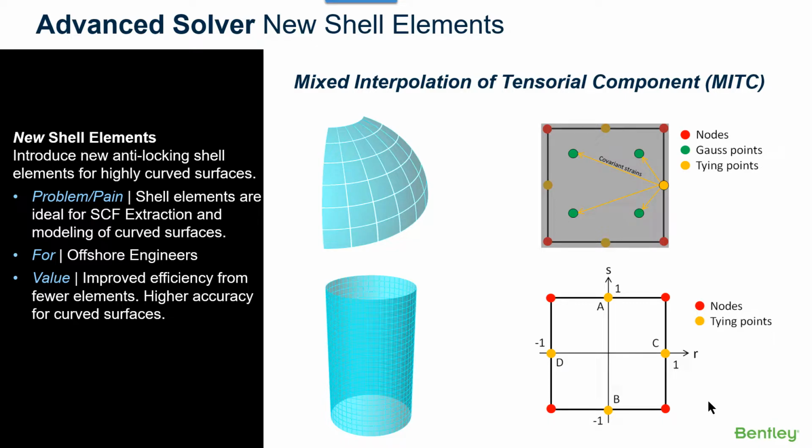element analysis. As we know, shell elements can have curvature, and it is known that theoretically, stiffening effects such as shear locking and membrane locking can occur if the elements have high curvature. The new update is to tackle this problem.